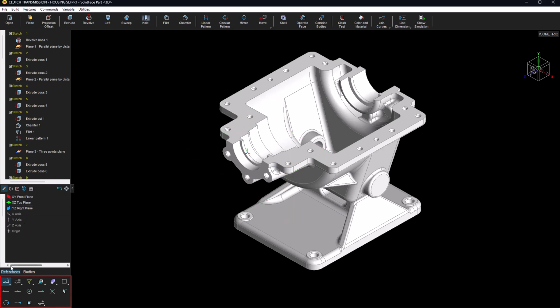In the bottom bar area, there are the blocks of functions for manual OSNAP, automatic OSNAP or auto info, filters, 3D views, render, and windows. In the upper right corner, there is the visualization cube and the dynamic model visualization buttons.